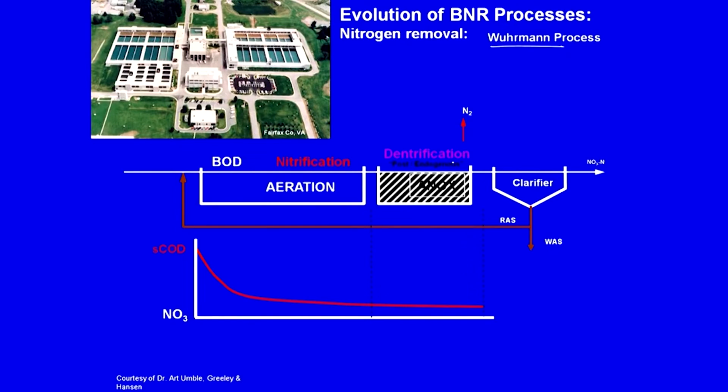That is endogenous respiration, if I may say so. Why? Because as you see here, by the time it comes into the anoxic tank, you do not have the carbon source anymore. So, they need a carbon source for cell synthesis. We looked at the reactions earlier. So, they are going to feed on their own cells, right, and here we have nitrate, as you know from the earlier case, and nitrate will decrease again in this particular system, let us see.